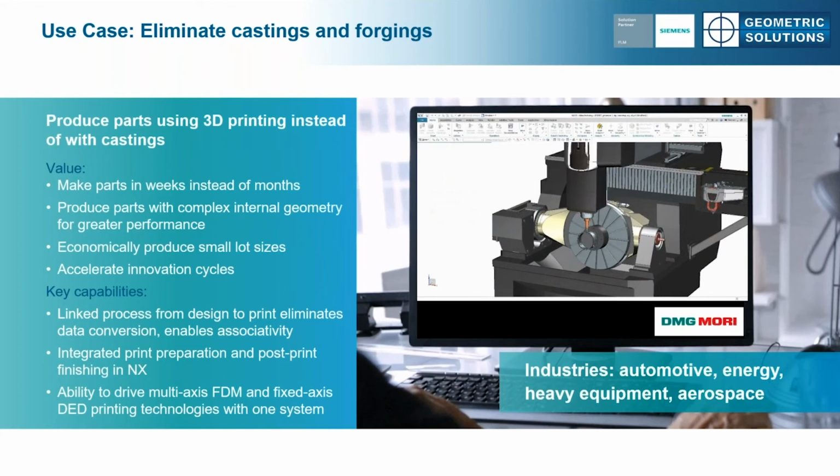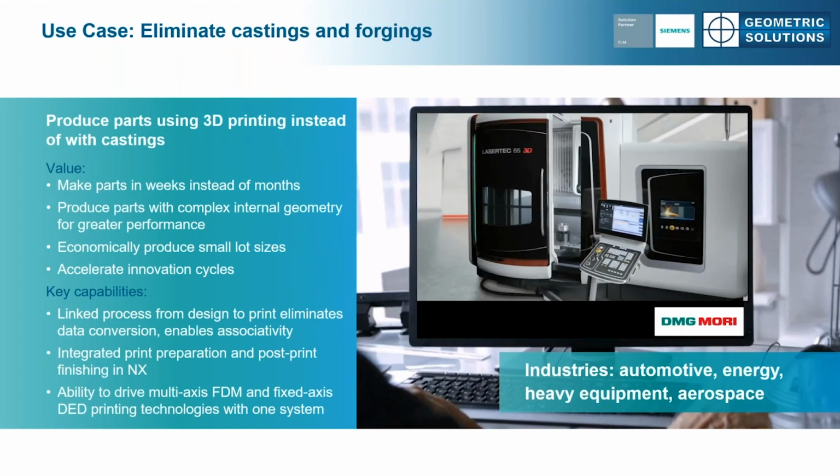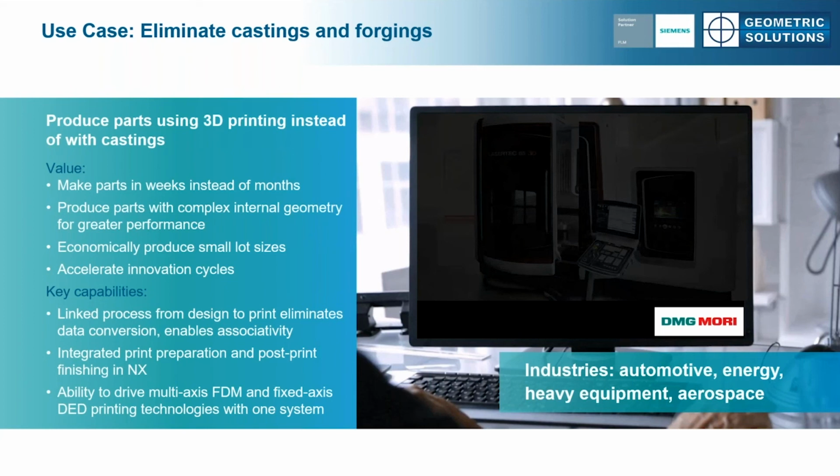Some of the advantages to this are that it's 10 times faster than fixed powder bed, and it can eliminate or reduce the need for those support structures that we had talked about. And the build envelope can be huge. As Curtis brought out, the one that he saw was up to 40 feet. And we can combine this with subtractive processes as well.